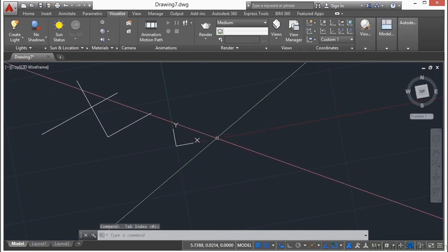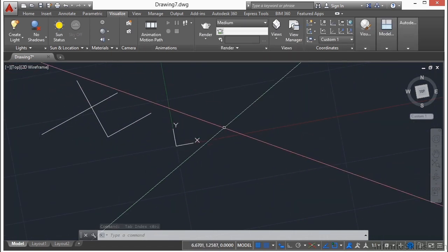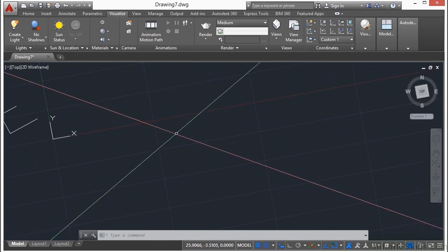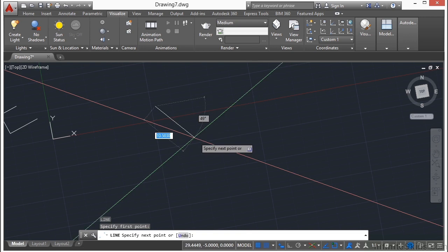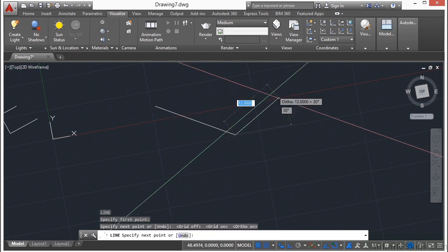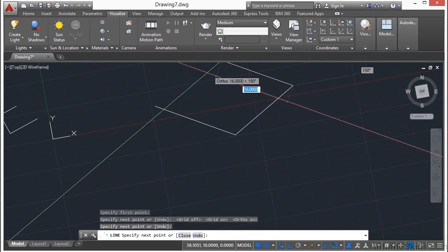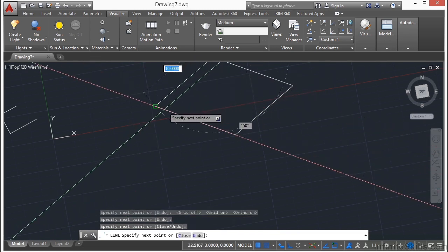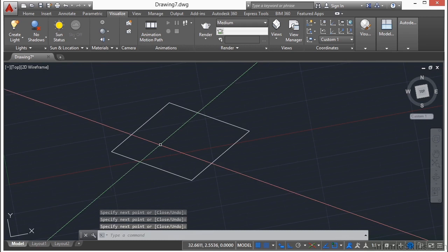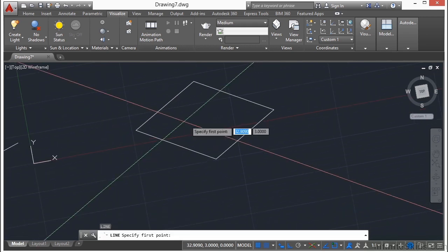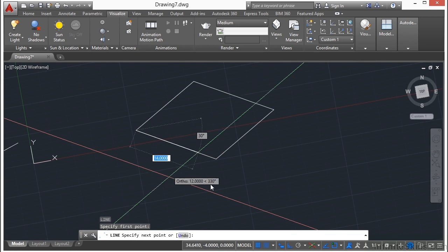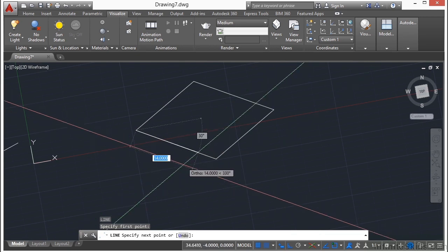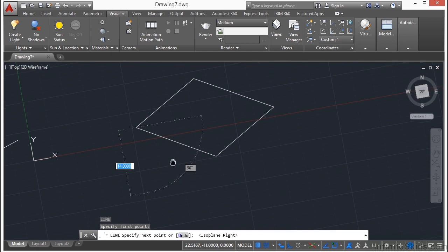So now you see here, you have a sort of skewed and diamond shaped set of crosshairs. So let's start drawing. If I draw here and I turn on F8, this will lock me into isometric mode so that I can now draw 3D isometric line work. So I can kind of draw an isometric view of a cube. I can come down here and I can press F5 to toggle through my different isometric planes.